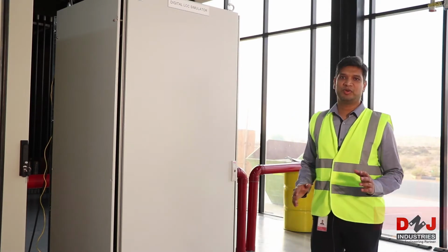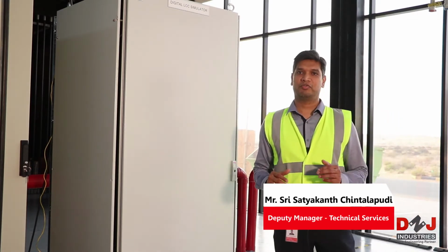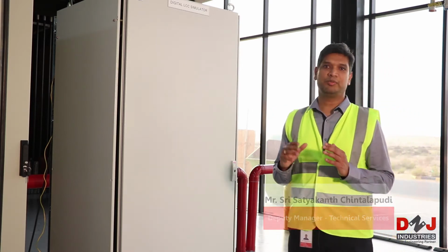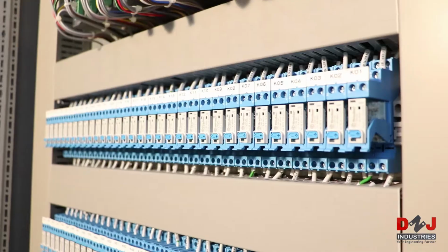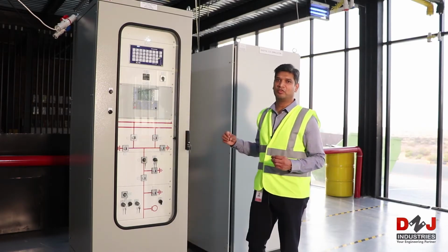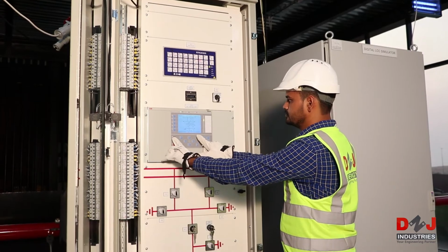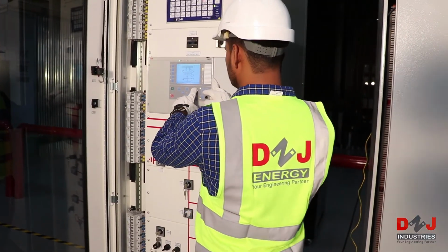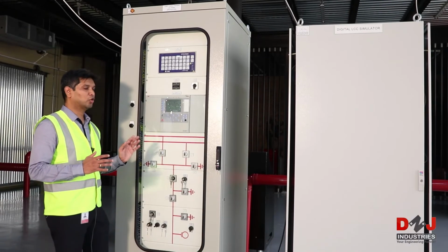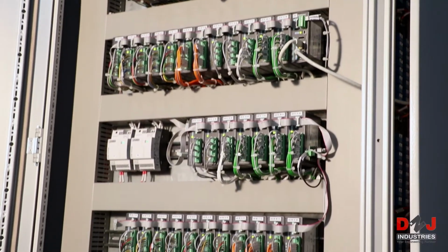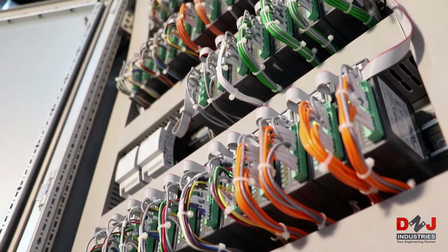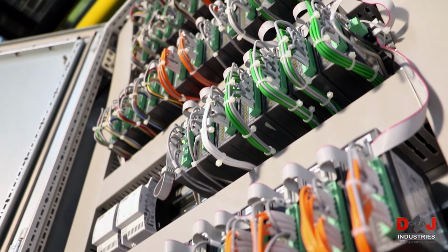Digital LCC test simulation basically comprises of three main areas. Digital LCC Simulator, which comprises of input-output cards, PLCs and contact relays. And LCC panel consists of initiators, BCUs, called bay control units, and mimic diagram. LCC sends open and close commands to the LCC simulator, which receives and sends the feedback in the form of NO and NC contacts to the LCC.